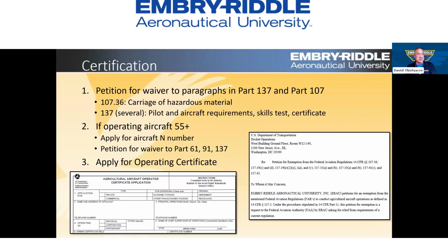All right, if you're not going to go that way, how does this process work? There are kind of 3 steps to it. As I mentioned at the start, up until August of 23, you had to go through the entire same process as if you were going to fly an R-44 spraying helicopter to get your Part 137, which meant going through the Flight Standards District Office. You had to get a check ride. They had to inspect your operating area and observe you doing the different things. So it was literally an FAA certification, including a practical flight exam. They just changed that in August, so you no longer have to go through that. That's what this is framing up as what you have to do now.